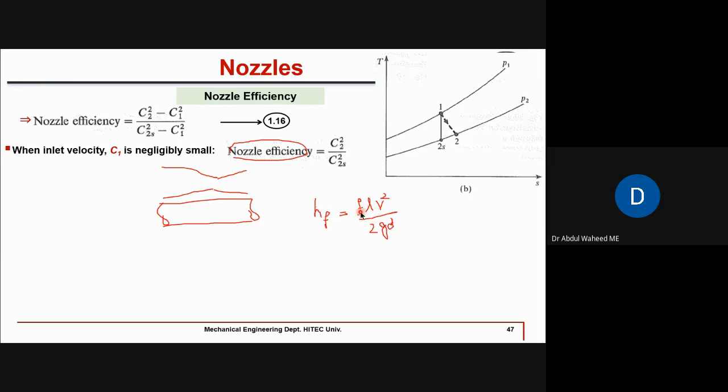Right. So that's why we can say that the nozzle efficiency is dependent on the type of material, means f, size, L, shape, D, and there are other factors like this angle of divergence, because now it's not a constant cross-sectional area. So that will also affect somehow this D, because D is not constant.